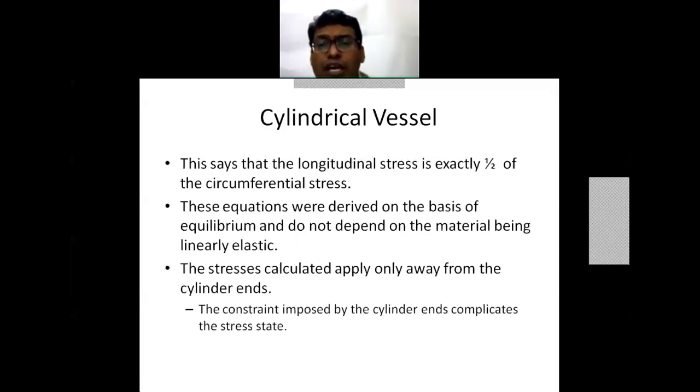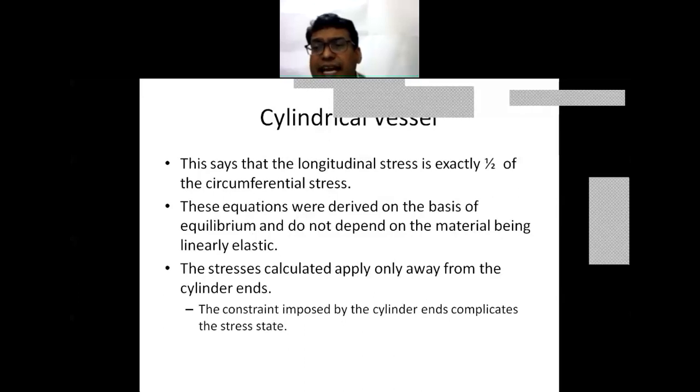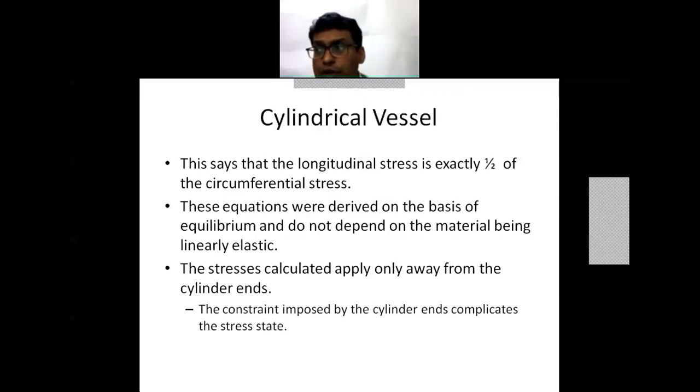Then the longitudinal stress is exactly half of the circumferential stress. Longitudinal stress is PD upon 4fJ, and the circumferential stress is PD upon 2fJ. Then the stresses calculated apply only away from the cylindrical ends.